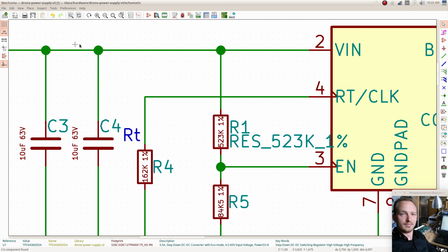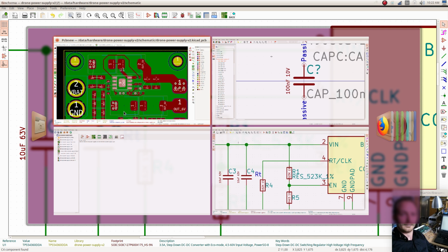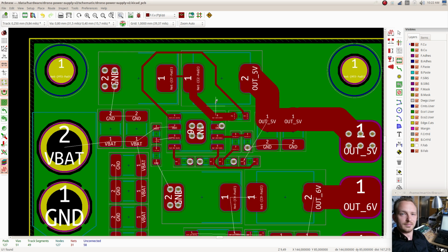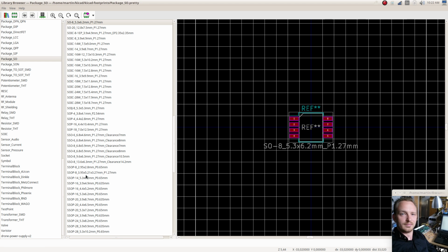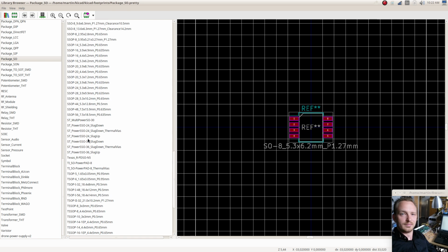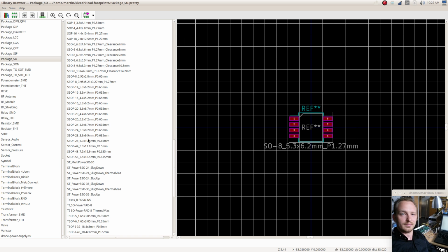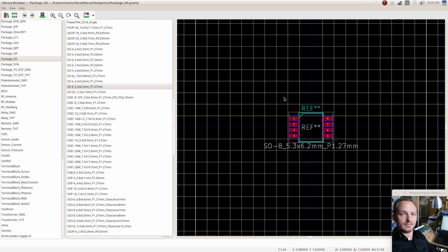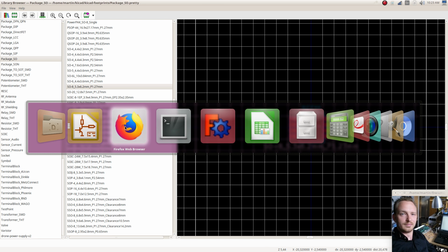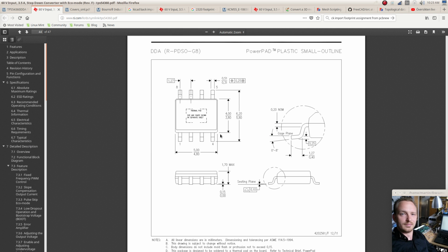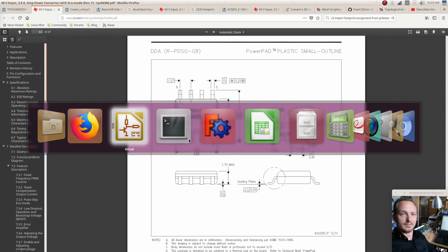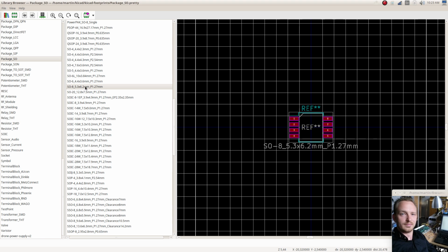if we go back to the right there. But then it's like 5.3. Really? Okay, so this doesn't seem to be the right package. Like 5.3, what would that be? This is just 5. So the length is 5, and 6.2 is the width. But it's not really clear, and I cannot pick this package because it's probably going to be wrong.